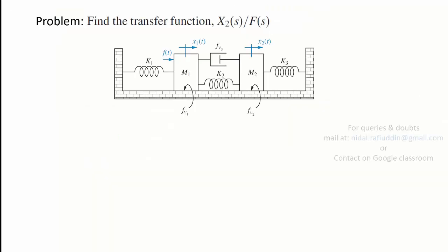Now we talk about the mechanical systems. Till now we have been talking about examples that we did in unit 1 in order to find the transfer function. And I used this example to allow you to understand the difference between finding the transfer function and obtaining the block diagram representation. So again, in this particular case, we're going to obtain the FBD. You always have to apply the basic governing rules in a network or mechanical system. For electrical systems, electrical networks, you have KVL and KCL. For mechanical systems, you have Newton's laws of motion or D'Alembert's principle.